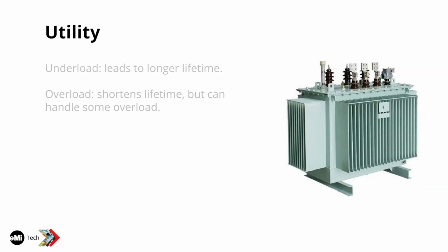As far as sizing transformers, I want to just cover underload and overload for the different sources because this can be something that people don't really realize. For transformers, if you underload them, it's no problem. They can just be underloaded for years and years. It just means they last longer. So there's no worry with that. If you overload them, it does shorten their lifetime, but it can handle some overload. So it'll just get hotter and last a shorter time. If you're overloading extremely and they're seeing really high temperatures, it can lead to a fire or explosion. So you want to somewhat be worried about that, but don't worry too much about sizing it exactly for the size.